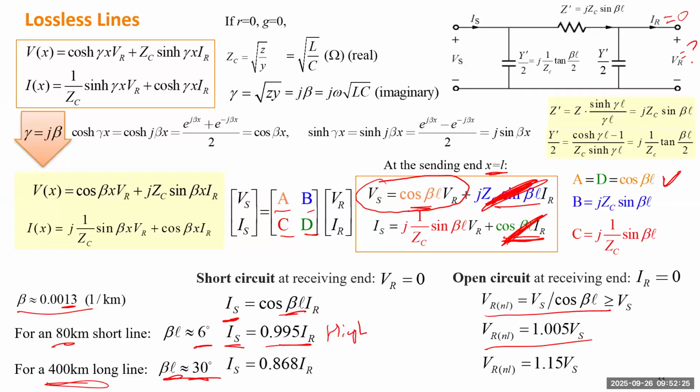For a short circuit fault, the source current will be about 86 to 87% of the load current. It's still very high. So if the fault current is very high, this value is still very high. So the conclusion is, if you have a short circuit, you need to do protection right away. Don't let the fault impact any generator, any expensive equipment.